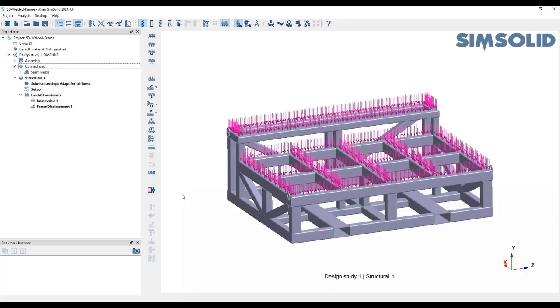Now just so you know, you do have other loading options as well. We won't be touching upon them, but you can use enforced displacement. So if you're trying to replicate real test data and you don't have the forces behind it, you can use an enforced displacement to emulate that distance traveled. We can apply inertia loads, gravity loads, so any G loads that you want, any inertia relief. You can do remote loads, bearing loads, hydrostatic pressures, etc.